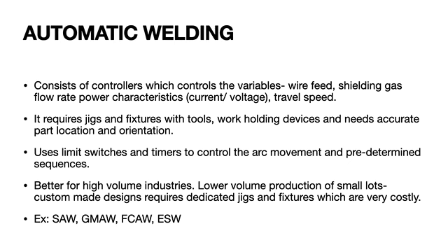These are basically used for high volume industries where we have a repetition of shapes, a repetition of the products which are produced. Whereas if you just look at low volume work, it may not be that ideal. That is because those may need custom made designs, and for the fabrication of custom made products, dedicated jigs and fixtures may also be needed, which will be a very costly affair.